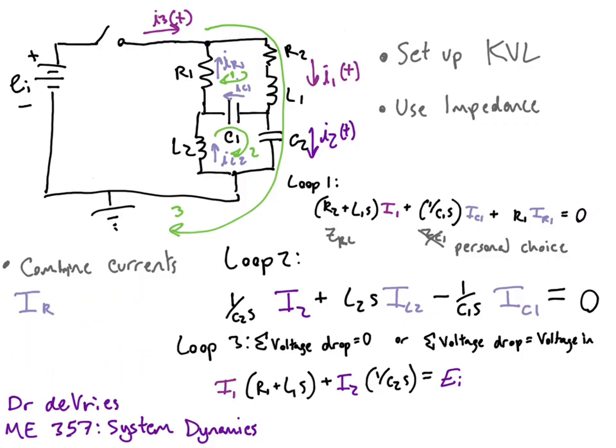I'm going to go back a little bit before we press play. I didn't add enough stops to this. For combining our currents, we're going to look at each node. For R1, we're going to have IR1, IC1, and IL2. For IR1, we look at the node with IR1, I3, and I1 because we want to limit our currents to just the number of loops, and so I've isolated the ones we care about using colors. So if we use Kirchhoff's current law,